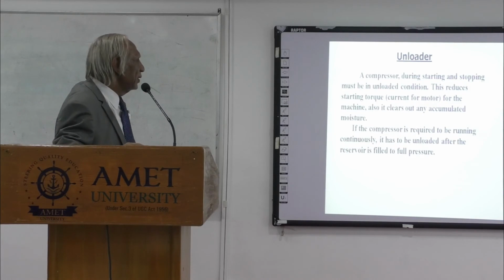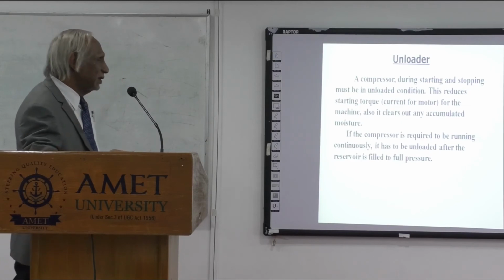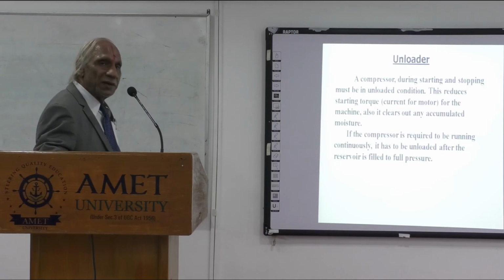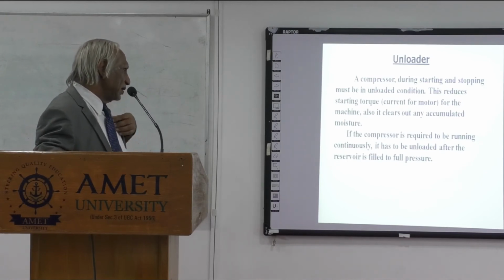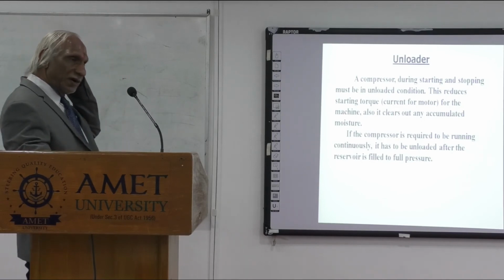Unloader: a compressor during starting and stopping must be in unloaded condition. This reduces the starting torque, that is, the starting current for the motor. Also, it clears out any accumulated moisture and dust. If the compressor is required to be running continuously, it has to be unloaded periodically after the reservoir is filled to the full pressure.